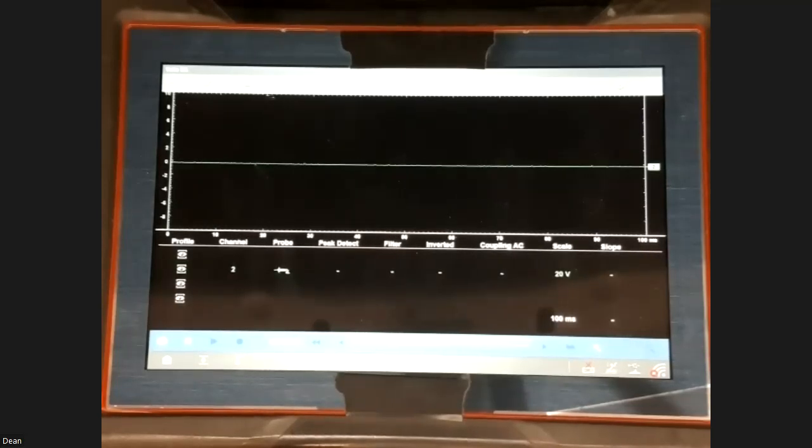Anybody in the questions? Nobody yet? Okay. You're going to have to let this battery chemically calm down before you can check the battery correctly. You're going to have a surface charge. You're going to have a refresh charge. So after an hour, you let the battery sit, and then you check it. Okay. It's 12.6, 12.59. Groovy. Is that good enough to start the system? Probably. Here's another way to check it.